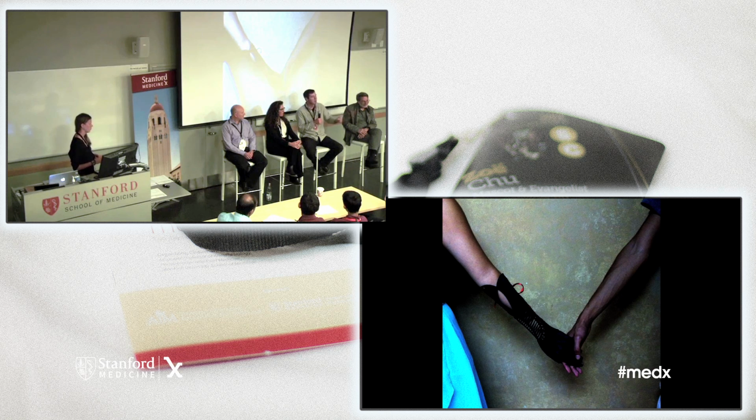Or you can have that scoliosis brace, for example, have parts of it that are Shore 7 and others that are Shore 60. And you can dither evenly between them. So that's what we're getting into now, these very interestingly biomimetic materials by mixing different materials simultaneously in a dithered fashion. And the dithering happens at a micro level, so you can't detect it, but you can change all of the mechanical attributes in any location of your part. So the sky's really open as far as all the ways you can mechanically change, compromise, or very deliberately affect mechanical attributes of a physical artifact now.